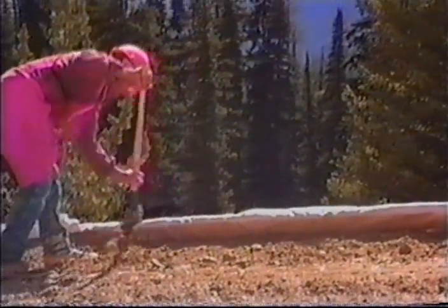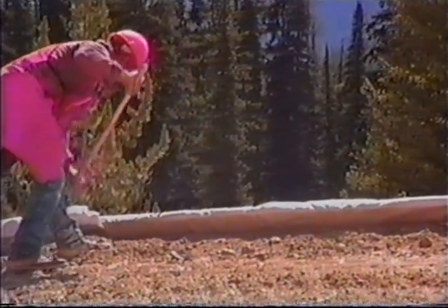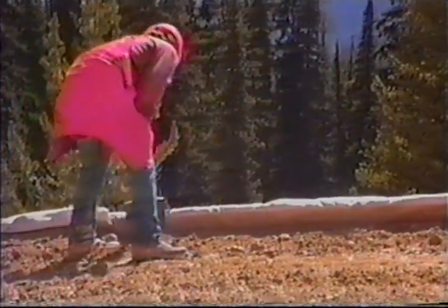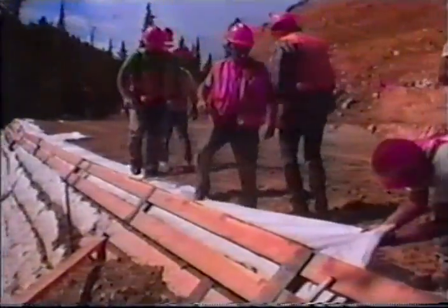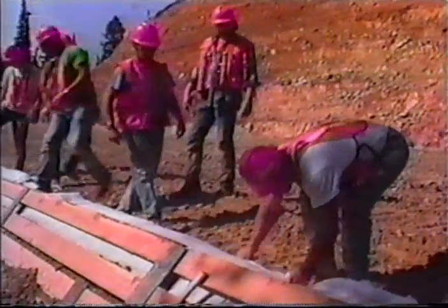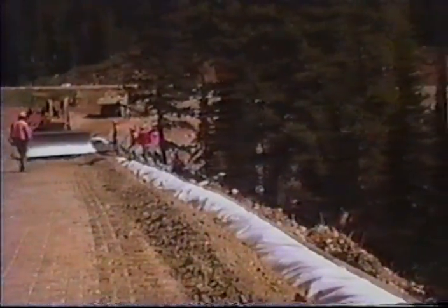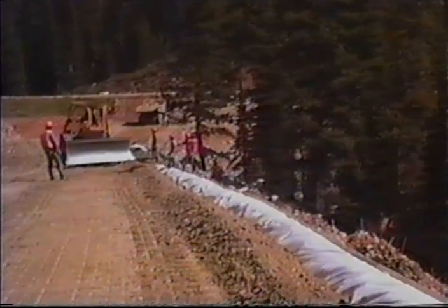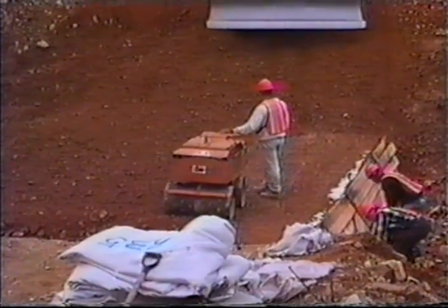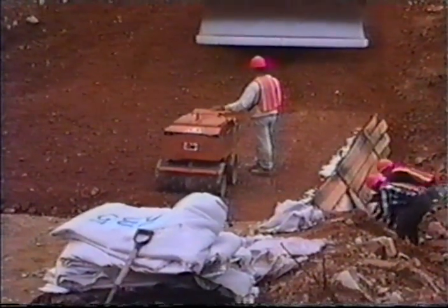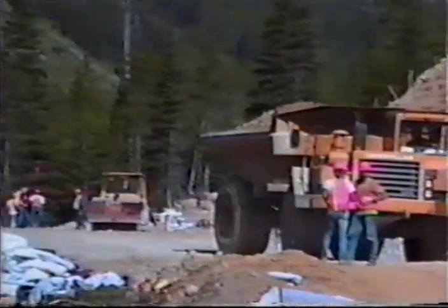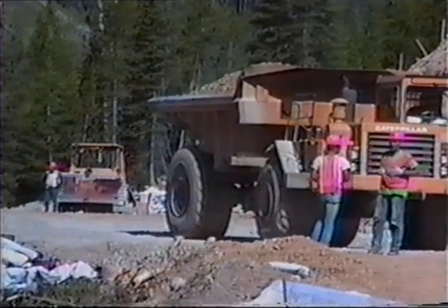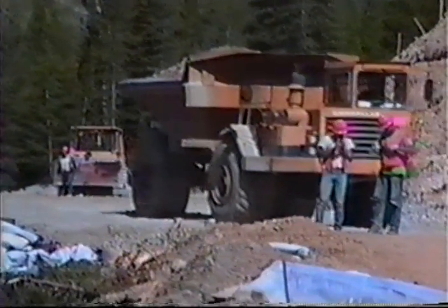To give the face of the embankment a tight and smooth surface, a windrow was formed behind the face. The tail of the geotextile was then lapped back into the windrow. A dozer carefully leveled material over the lap, anchoring the material in place. These details permit equipment to work close to the edge, so the soil can be compacted more thoroughly. This improves the stability of the edge, reducing sloughing.